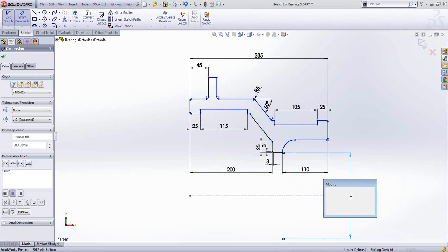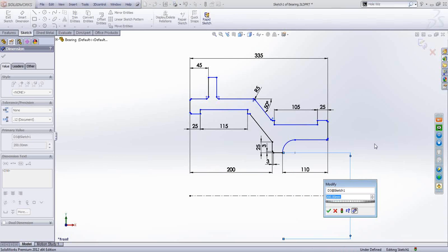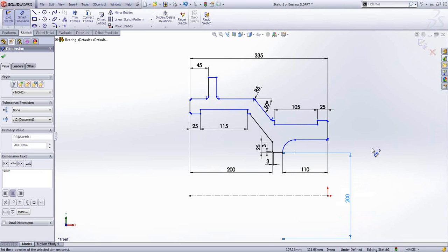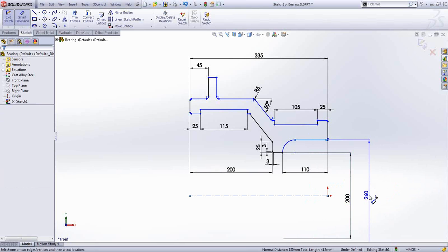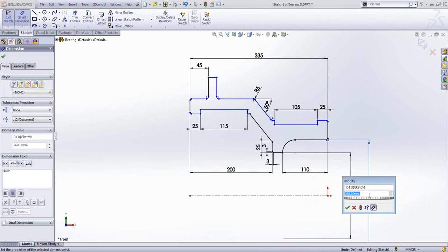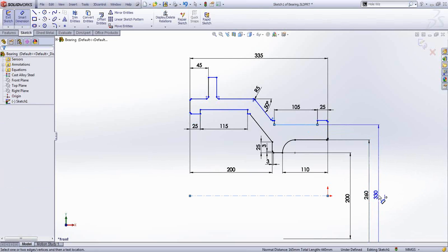In SolidWorks 2012, after you place your first dimension, you notice there is something different about the icon there. You notice that it is showing the center line and the diameter icon. So what it essentially is saying is, don't again pick the center line, just keep adding your diameter dimensions. So it has retained the center line selection, and now all you have to do is place your diameter dimensions.